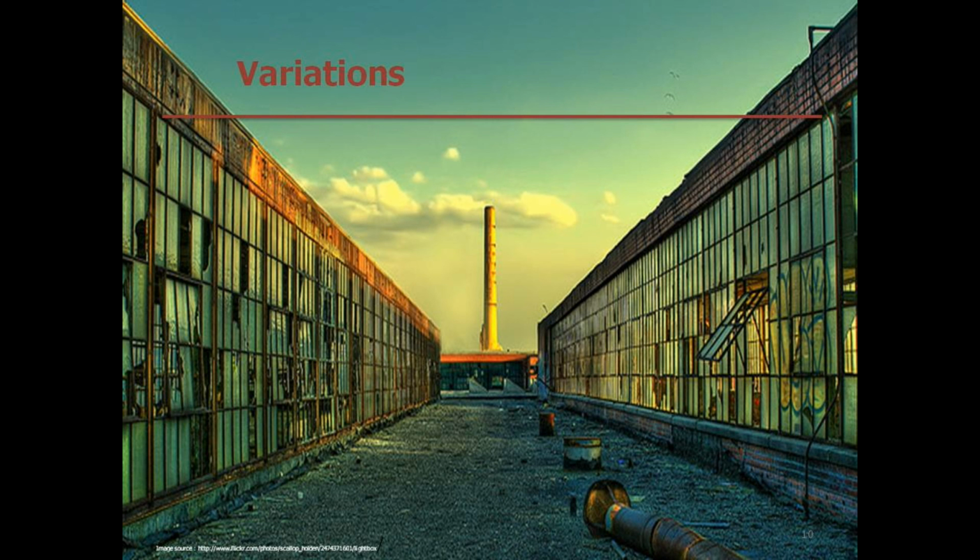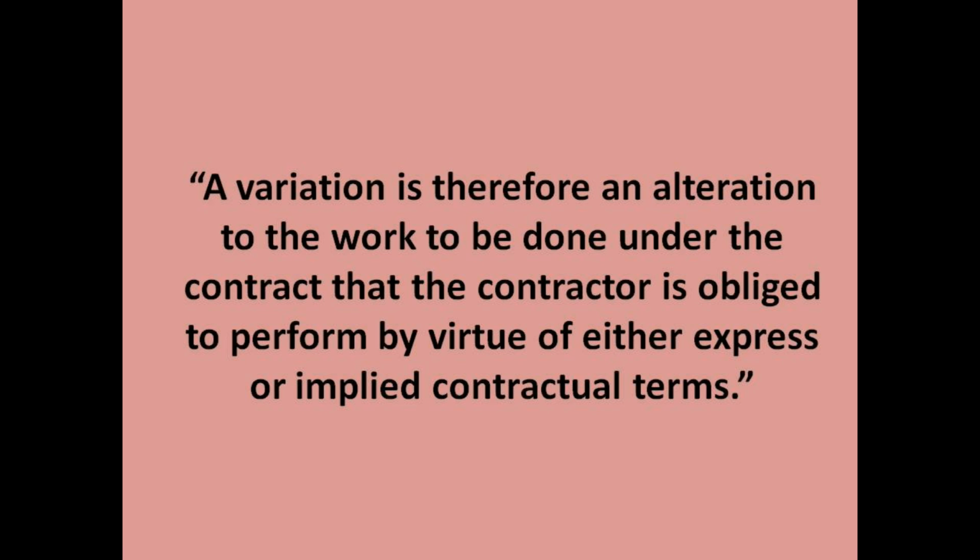It's inevitable that throughout the progress of the works there are going to be variations, regardless of how well the working drawings, specification, bills of quantities and rates have been put together. So variations are important to be clearly documented, quantified, and communicated to all parties, so it's clearly understood where the overall cost is likely to finish up compared to the original intention of the estimate, and also the tender result.